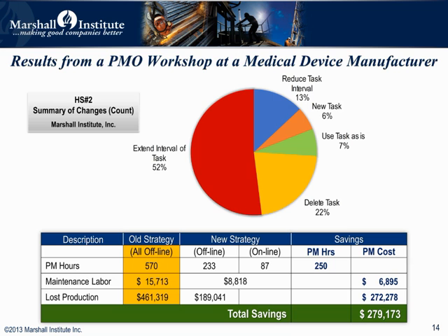Optimizing the PM program on this line resulted in eliminating non-value-added tasks, moving some PMs from offline, where the line had to be down, to online, where the line could be kept running, and extending the interval on more than half the tasks without harm.